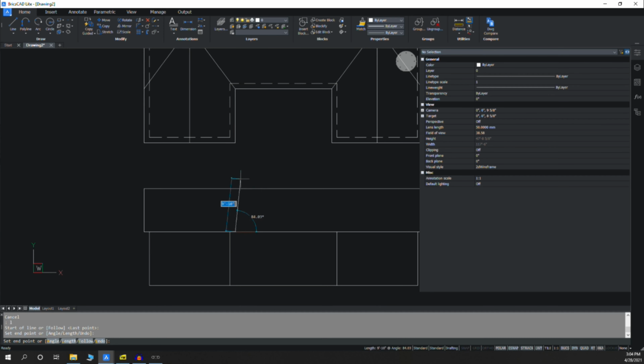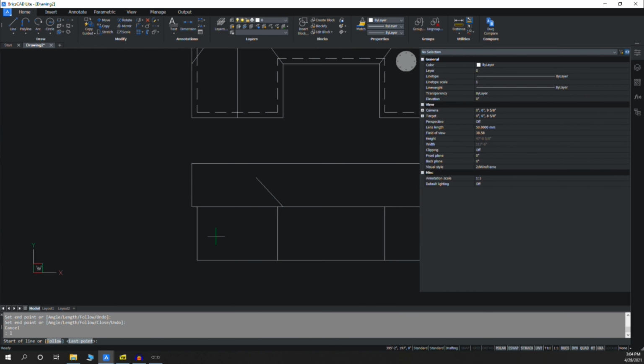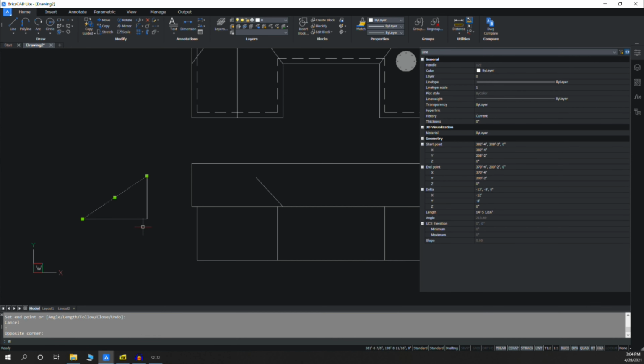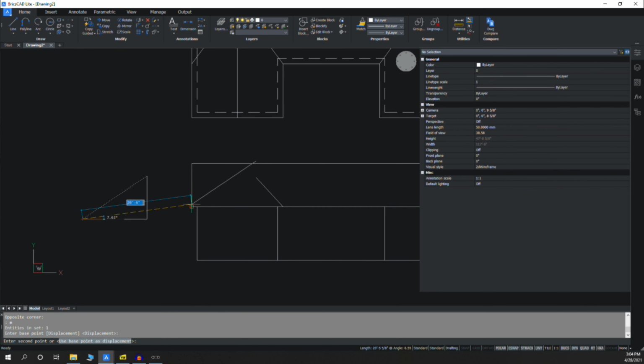Remember, it's a 12-inch eave. And then we've got some sort of slope coming up here. I'm just going to draw it in place so I remember where this eave ends. Remember, this is an 8/12 pitch, so we got to go over 12 feet, up 8 foot. And as you notice, it's a little bit steeper. So now I have an 8/12 pitch line.